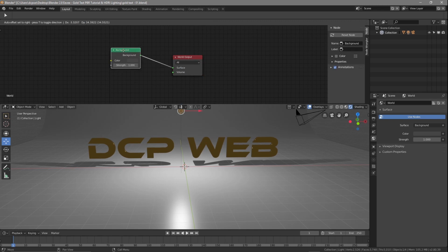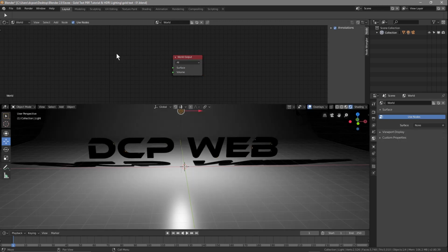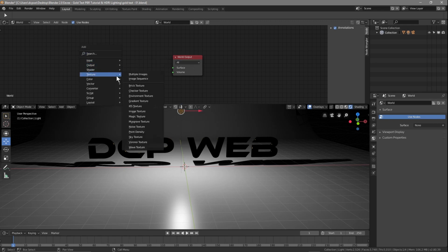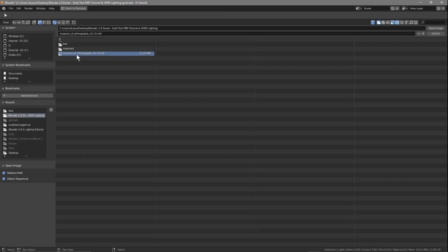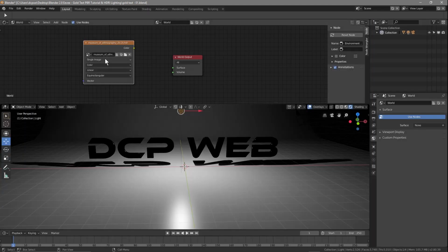So we want to click on this background. We don't need it, so we can just delete it. We'll delete the background. We're going to press Shift A, and we're going to insert an environment texture here. And then we're going to open this. It's called Museum, right? This image we just downloaded. We're going to open that one. Click Open, and pretty much everything you can leave in here the same. We can play around with these in a minute, and we just drag and drop this to here.